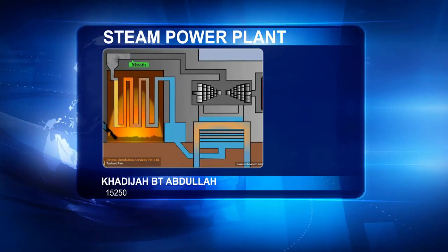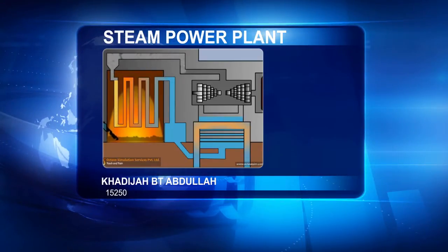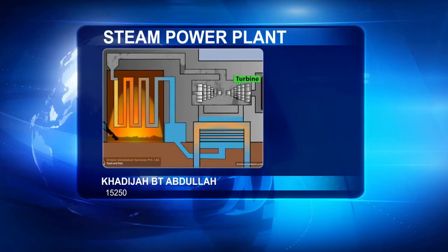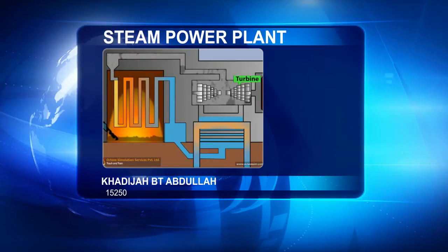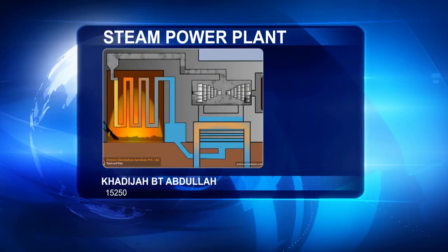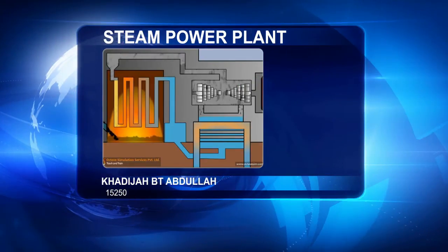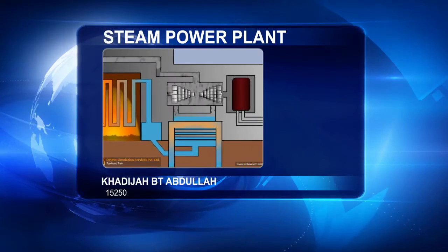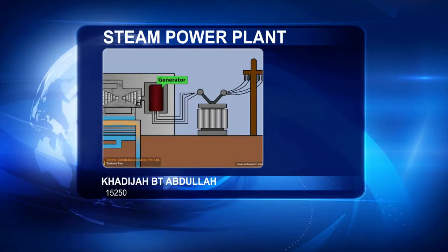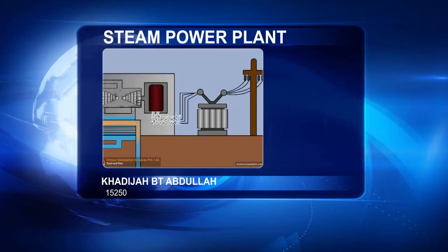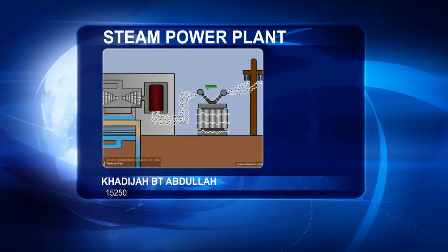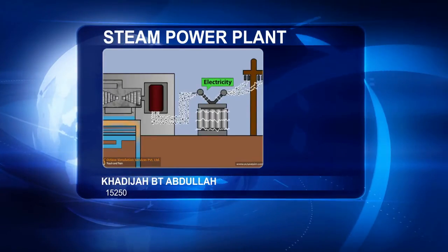The steam is transferred under pressure at high speed through large pipes to a turbine. It is this pressure and flow that pushes the blades of the turbine, causing it to spin. The turbine is connected to a generator that contains the rotor. As the generator rotor spins, a flow of electrons is created in the stator. It produces electricity that can be stepped up in voltage through the station transformers and sent from the station across transmission lines.